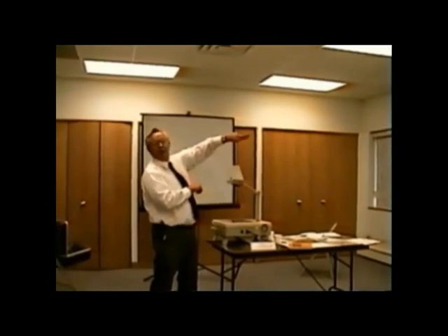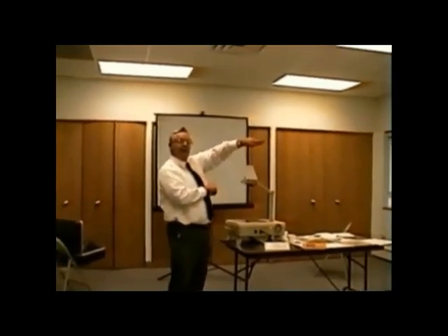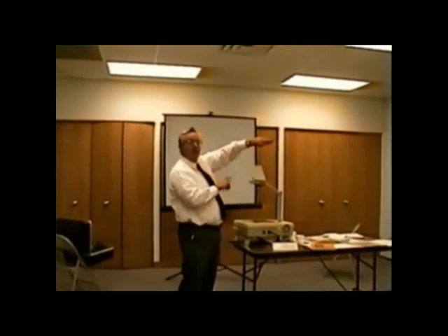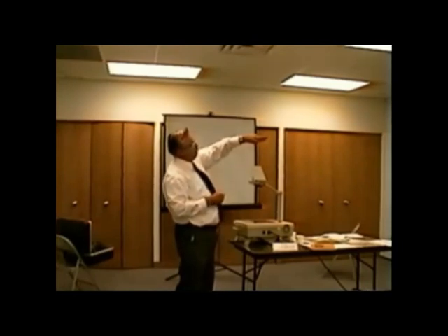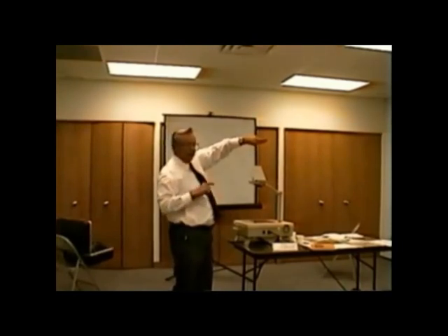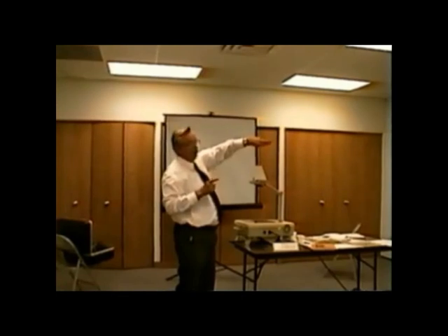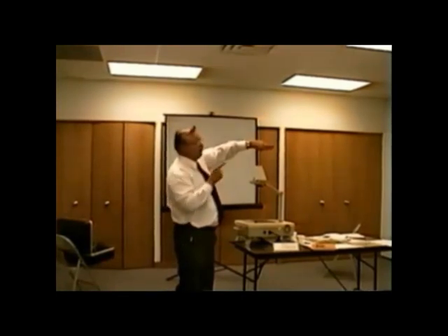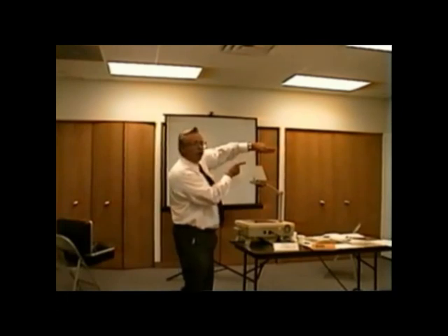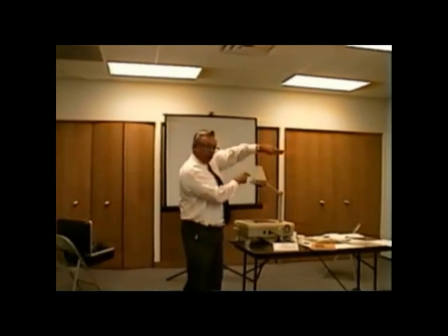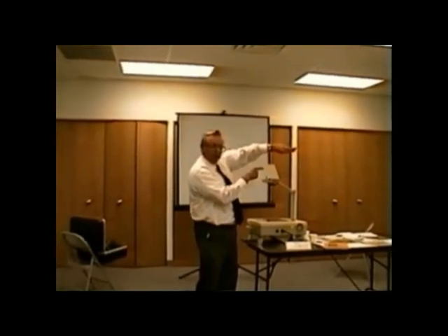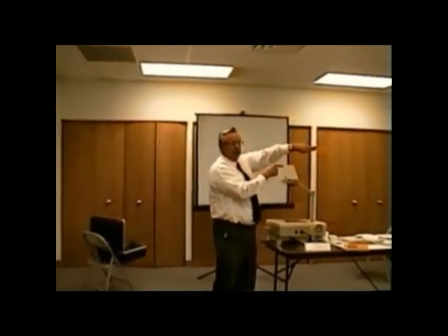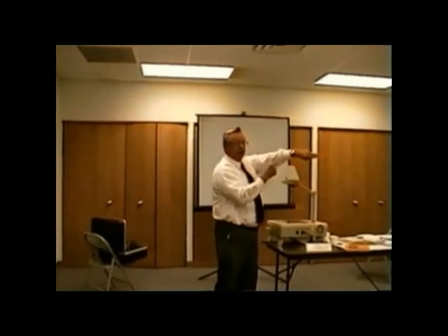So let's say it goes all the way up to 1 inch. Now it sits there and the furnace is operating and it's at 1 inch. We've got terrific venting, okay? Now the furnace shuts down. And if we looked at the magnehelic gauge, it would say 1 inch, 0.9, 0.8, 0.7, 0.6, 0.5, 0.4, 0.3, 0.29, boom, and it opens up. So it's got to go below the set point to open, but it's got to be 1/10 negative better to close. Is that clear?